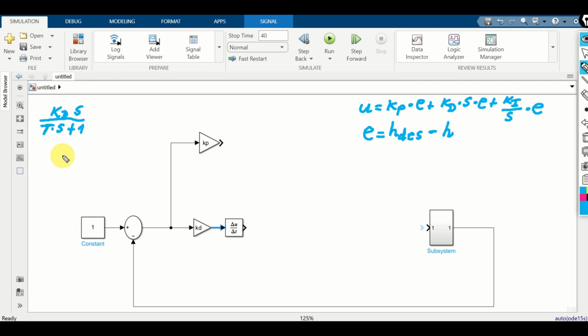After 1 over t frequency, we will see that the transfer function, or better to say its Bode plot, will decay. And this will actually limit, or better to say, make sure that the high frequency components are not exaggerated and they're not amplified.